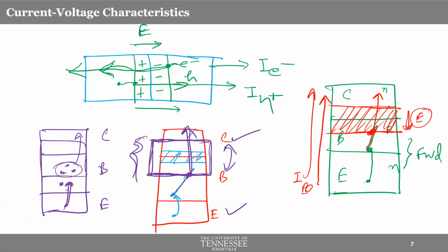within the base. So all you have done is increased the number of electrons that can successfully flow from emitter to collector. How? By increasing the strength of the reverse bias in the base collector junction. Well, it might sound counterintuitive: hey, I'm increasing the reverse biasing, so that should discourage the current.